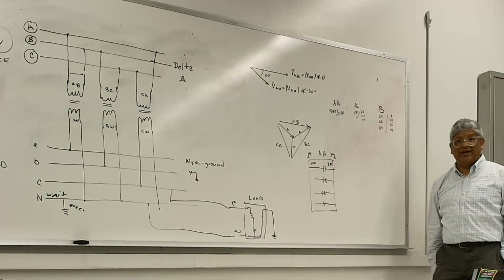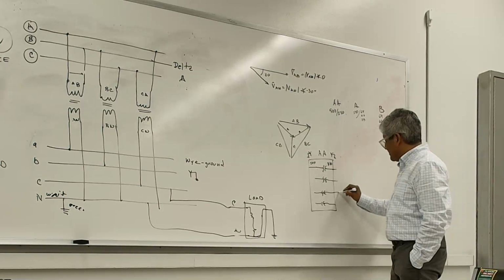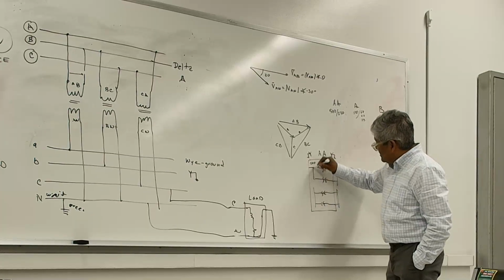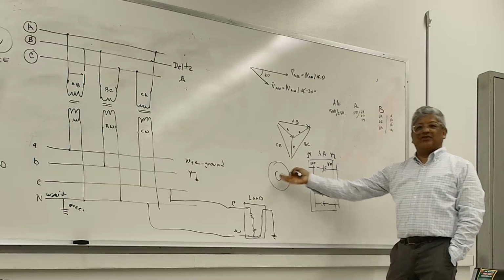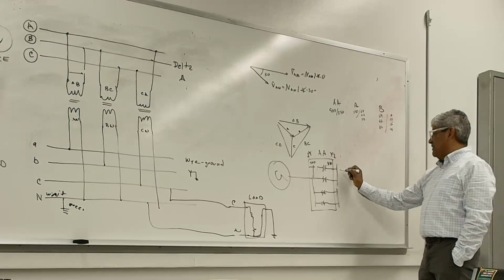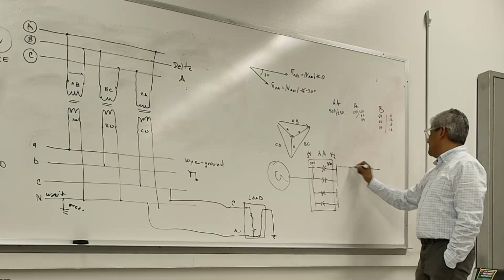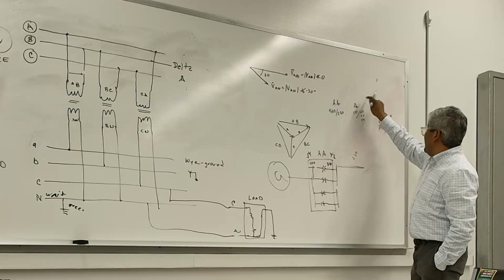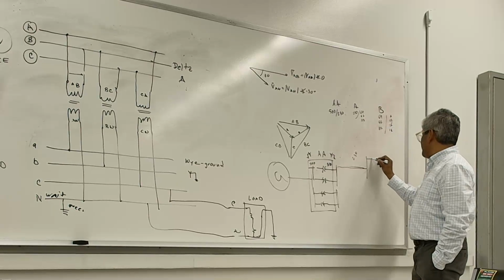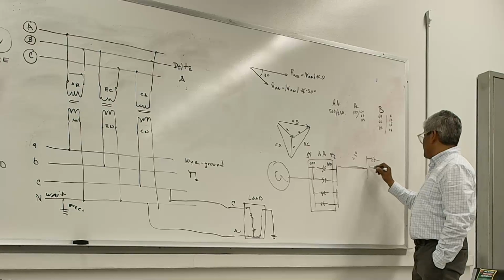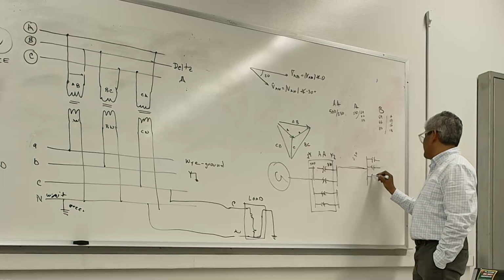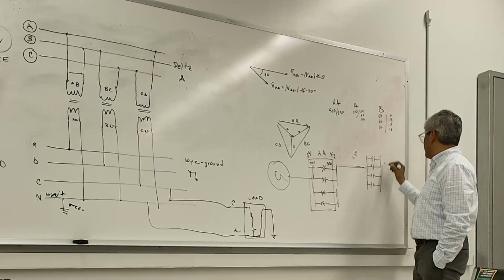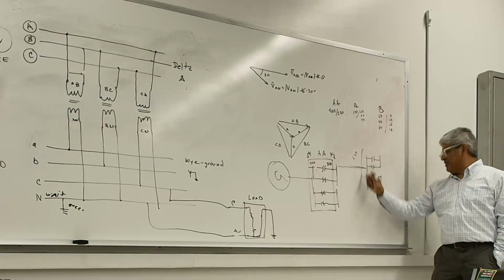So that's a substation. That's a facility, right? From here, they obviously connect these transformers like this to this bus. They make a bus. Here's the source, the generation, I'm going to say for now. From here, then they have lines. They have a line from here, and this line obviously is 230 kilovolts, and they go to an A station. So an A station is fed on the primary at 230. Here's another 4 transformers. Maximum capacity for Edison substations, and PG&E I think is the same, is 4 transformers per substation. So here's the other substation.